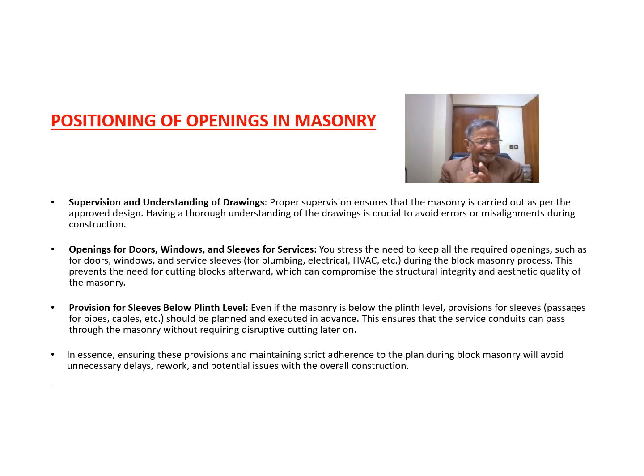Provision for the sleeves below the plinth level is also necessary, so that you can start the masonry from the plinth level. All the sleeves should be kept and left earlier. Adherence to the plan during the block masonry will avoid unnecessary delays of the project. So all these things are to be done for the openings in masonry.